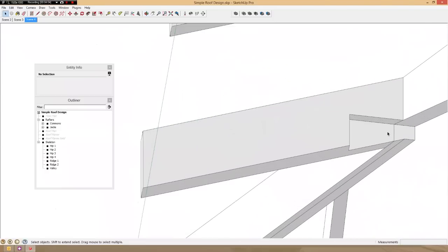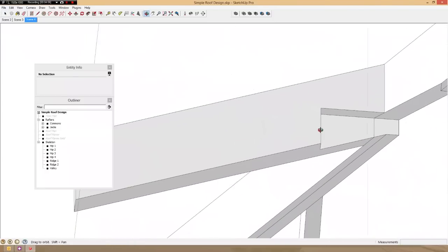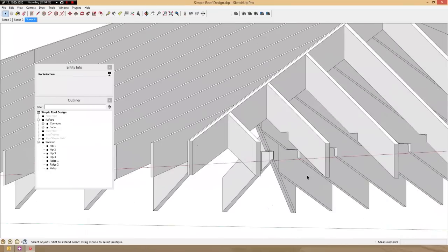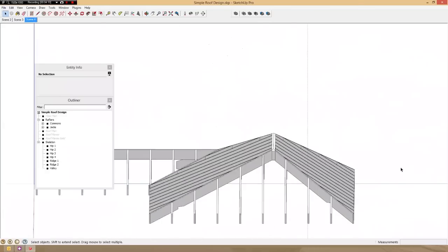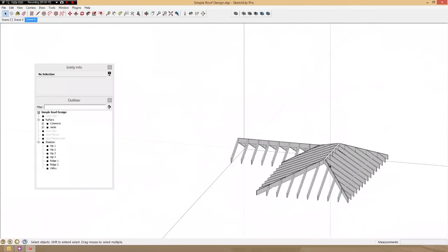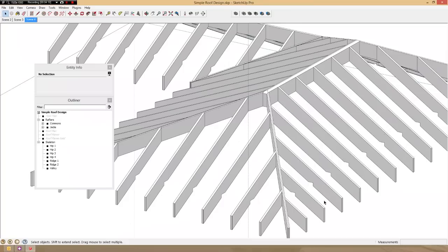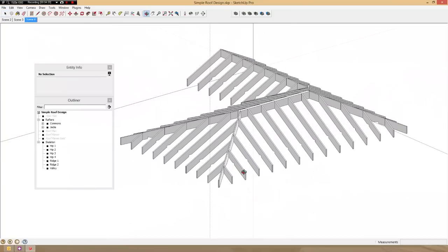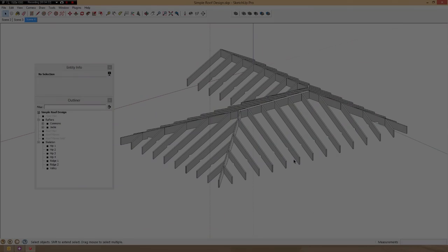These little jacks there are kind of awkward, so I think you might adjust your layout to avoid that. But there you have it, a completely developed roof system with seat cuts. I'm going to let you go ahead and install your own freeze blocking and such.